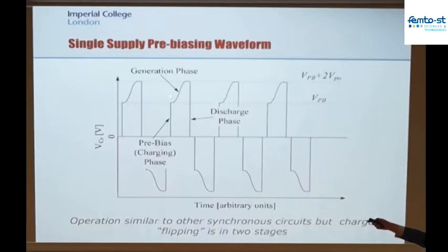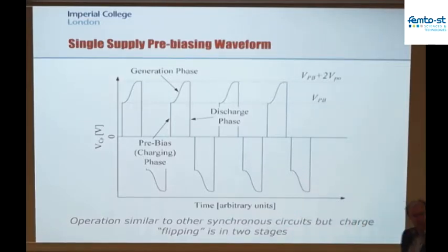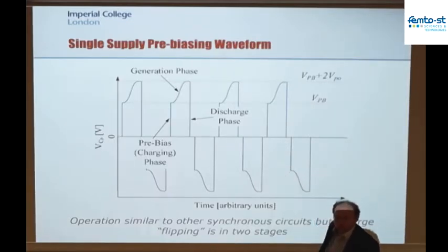Pre-charge the piezoelectric material to a certain value, then allow it to move, and I see approximately a sinusoidal voltage while it moves. Then I discharge it again. So effectively, I'm borrowing a bit of energy here in order to get the right force on the device, optimizing the mechanical coupling into the system. Then I allow it to move where it generates power, and then I take that energy and I put it back into the power supply. So I've got a fundamental difference here. I've got more energy to take out than the energy that I borrowed in the first place. And of course, this is like V2 squared minus V1 squared.